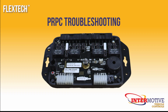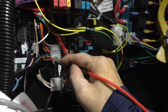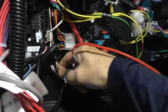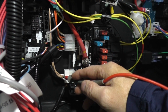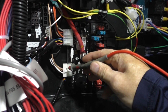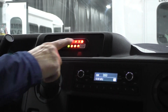PRPC troubleshooting. On the PRPC, checking the voltage on the red and the gray wires is one way to tell if your PRPC has power or if you're not getting any function. This brown wire right here is the input for the lift door open. This one is important to check if your interlock is not working correctly. Pin 10 on the input connector is always the lift door open signal. When a ground is applied, you will see the door ajar light illuminate on the gateway status LED panel.